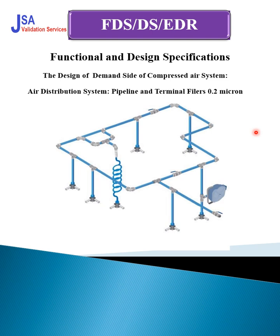If you require a 1000 CFM compressed air system, and the vendor designs a 50 CFM system, then it will be of no use. So you have to clearly mention how many user points you require for the compressed air system, what the demand is at that point, what pressure you require, and the CFM consumed by the machine. All that should be defined in your user requirement specification.